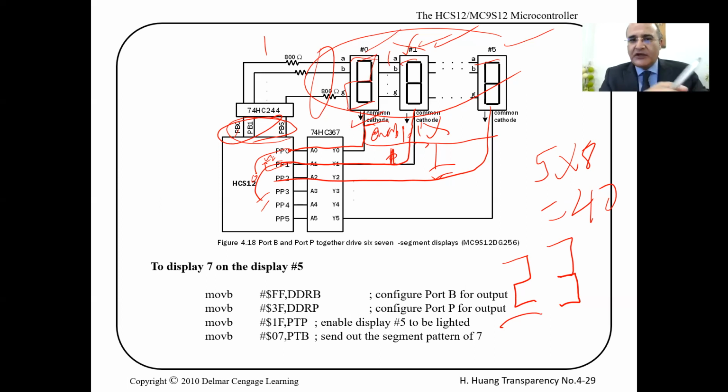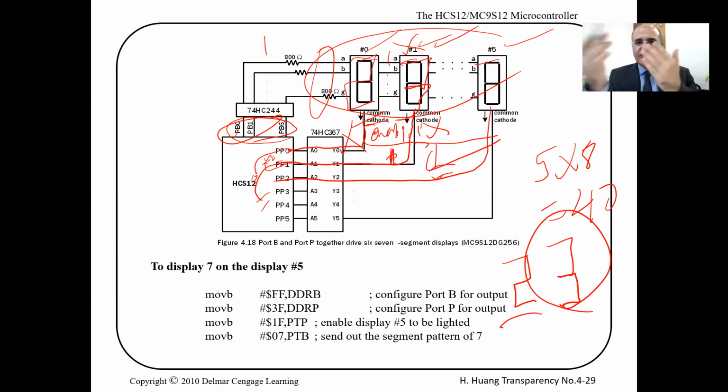Then, real quick, in terms of milliseconds, you enable the other one and disable the first one and send the 3, and you see the 3 on the enabled one. Do the switching really fast: enable this, disable this, enable this, disable this, keep switching the enable every 200 milliseconds, 300 milliseconds, or 100 milliseconds. Something really fast that your eye cannot see the switching.